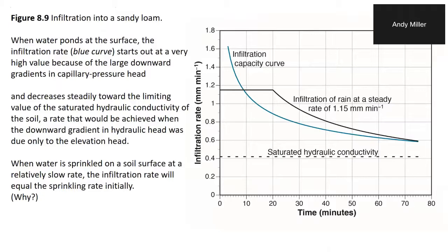Okay. But if you change the infiltration capacity of the soil by taking away a lot of that, then you're actually going to have a soil that's going to have a lot more runoff because it can't infiltrate, because the infiltration capacity has been reduced as a result of the things that we've done.